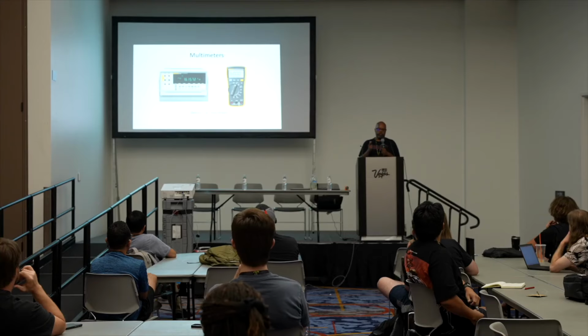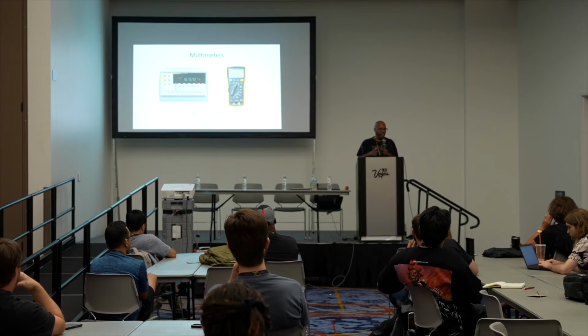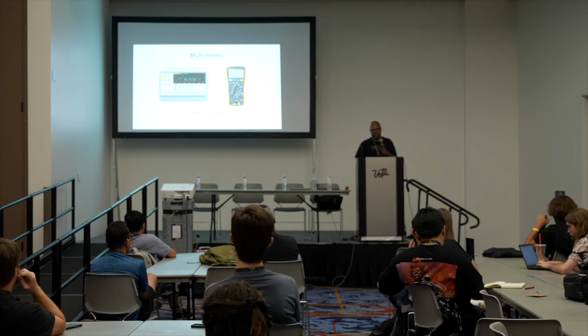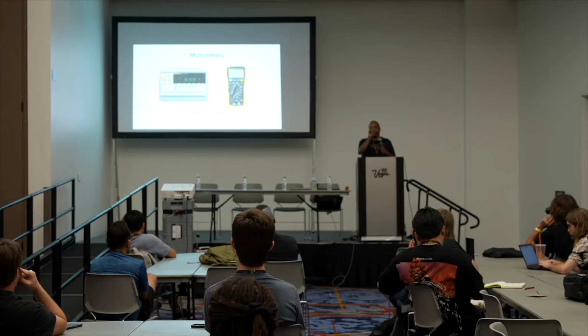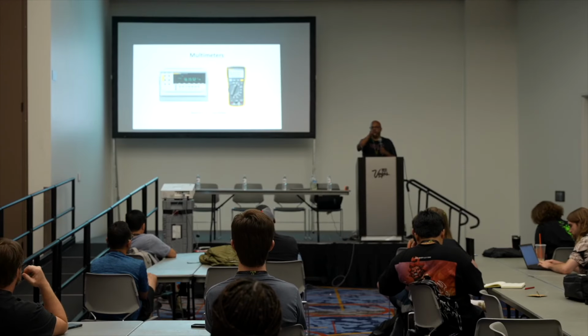One way is with multimeters. So the first thing you always have to have. You gave some out, Sydney, yesterday, right? A multimeter is just a little, you get like a handheld one or a bench one. And basically it tells you the voltage between 2 points. So you can tell if something is high or low. It can read the current, how much current's going through there if you need to know. It can read resistance between 2 points.